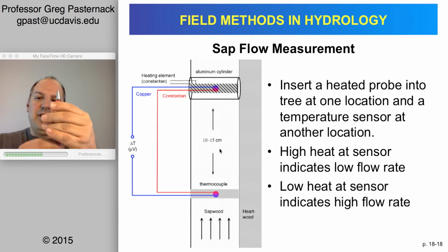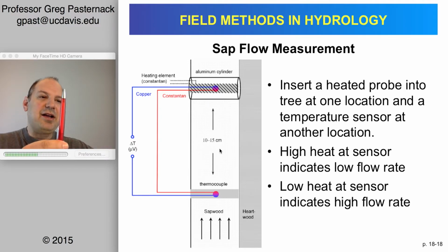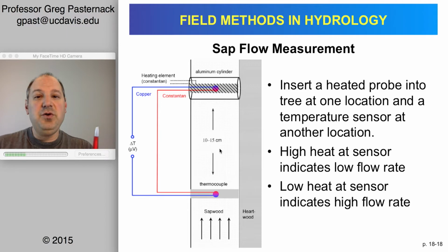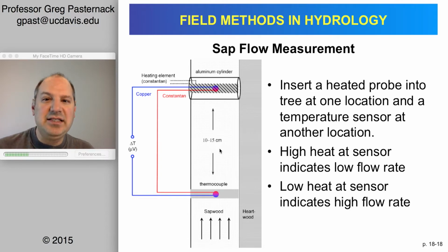Well, what's going to happen is that source of heat is going to primarily be moving in the direction that flow is going, but still some is going to move upslope too because diffusion is going to carry it that way. And if you go back to the Environmental Tracers video podcast, you'll see many examples of plumes. They're not necessarily heat plumes, but heat works the same as contamination and everything else, pretty much.